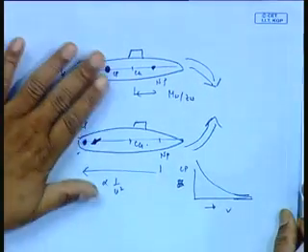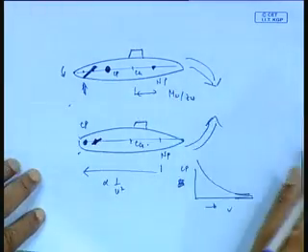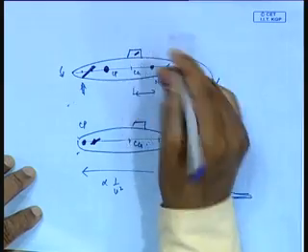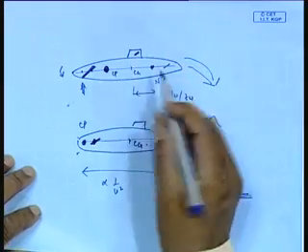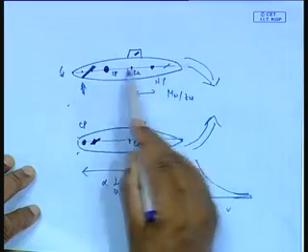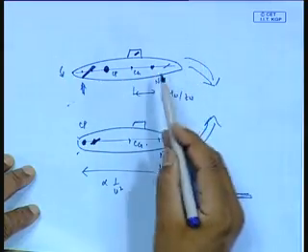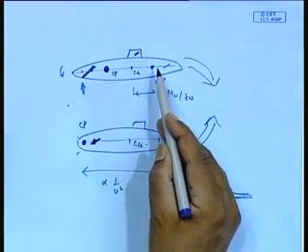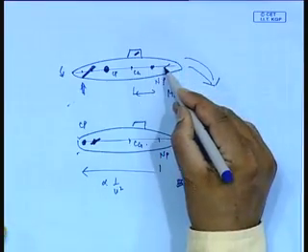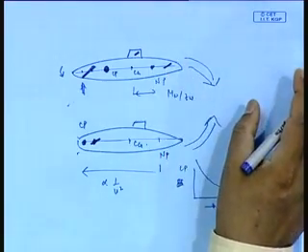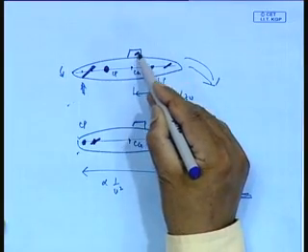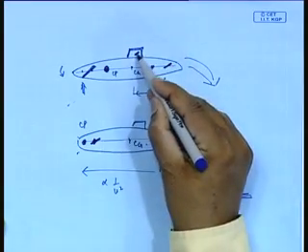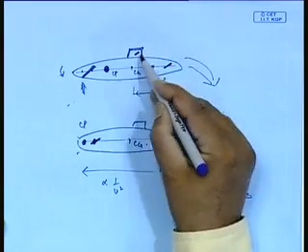The second thing I tell you is connected to this. Before that, what about the bow plane? The bow plane is either here or here. Typically, the bow plane is actually forward of even the neutral point, quite on the forward side. If you have gone to Vizag and seen a submarine, you would see that it has a plane at the very front, but that is a very old design. Nowadays many of these planes are on the sail. This is called a sail, and instead of on the bow the plane is on the sail. So it is not that much forward, it is somewhere here.